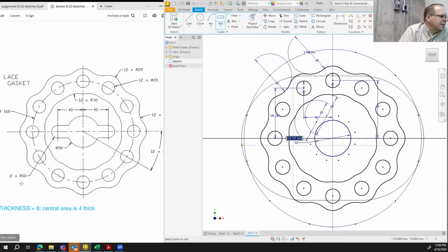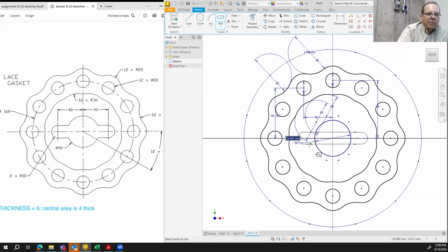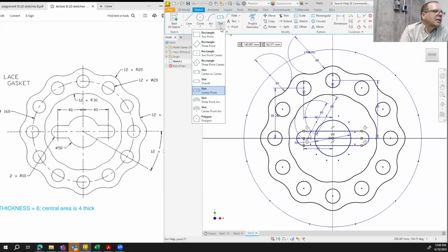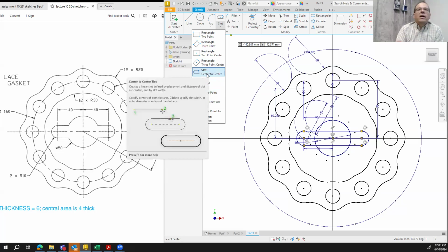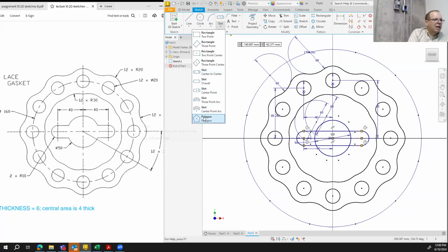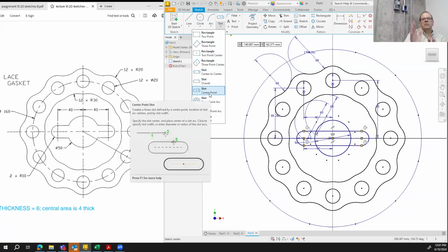And it has a radius of 10, so we have to put in 20 because it thinks about this other circle. The slot length refers to the center point. It depends, right? There's this slot right here, where this is the distance between the two centers. This is from the center to the center of the circle. So center of the slot to center of wherever the half circles are.